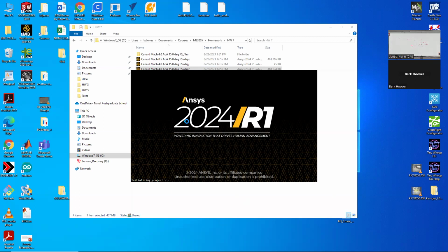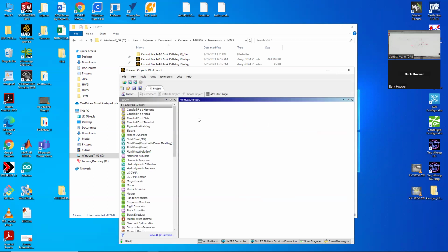you get such a huge expansion over the top of the wing. The Mach number gets quite high up in there and the pressure gets phenomenally low. And so I think there's some unsteadiness inside that pocket that the code is trying to resolve. And I actually ran one, I tried to keep this one small, so I think it's just under 500,000 points. I ran one that was about 2 million points and it converged better, but cost a lot more.